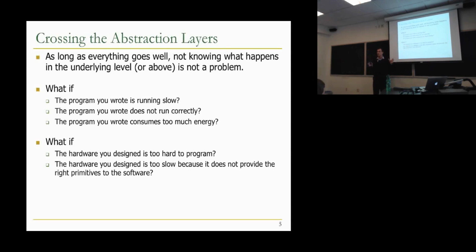Because if the programmer knows what they're doing, if the data is going to be reused by the program, they can use the first instruction, keep this in the cache. If they know that they're loading data that's not going to be used later in the program, they can use the second instruction, load this data, but don't keep it in the cache. Throw it away. I'm not going to use it. Now the programmer or the compiler can optimize the program much better, right? And this is one primitive that the hardware can provide to the programmer or the software.